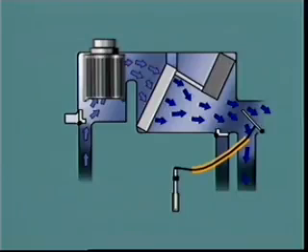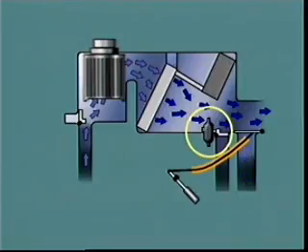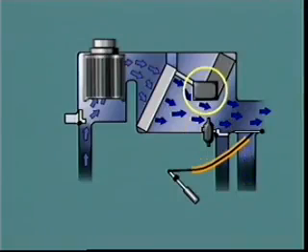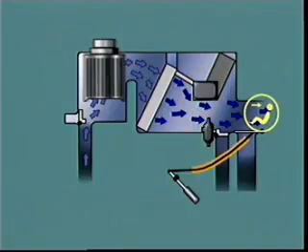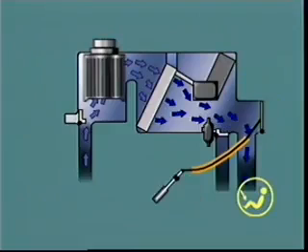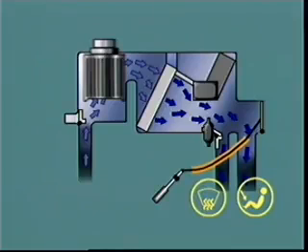These flaps can be controlled by cables, by vacuum servos, or by electric servos. In this way, air can be directed to the face ducts, floor ducts, window demisting ducts, and rear passenger compartment ducts. A fan driven by an electric motor is used to assist the air to flow through the passenger compartment when demands are high or when vehicle speeds are low.